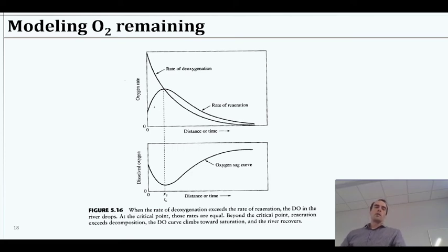That means almost immediately we start having reaeration. If we had water fully saturated with oxygen, the reaeration is 0. But since we didn't start at the saturation point, we're not starting at 0 reaeration. So typically there's constant reaeration, because a natural body of water is going to have some natural organic matter and stuff like that.